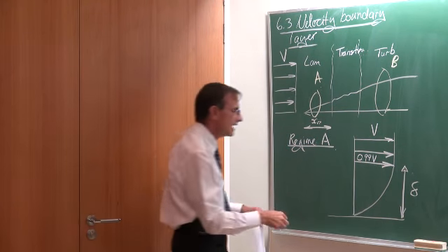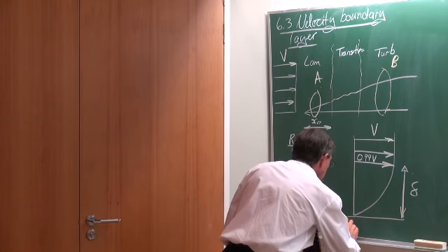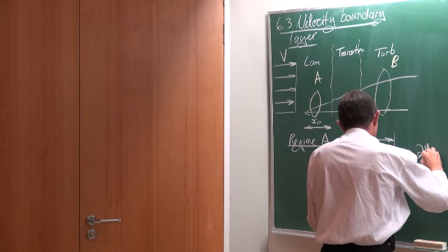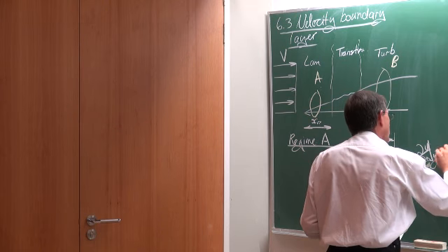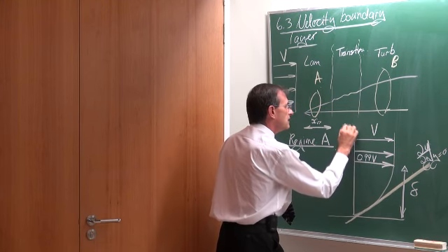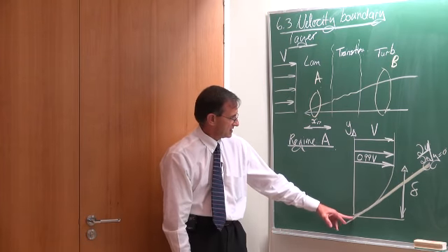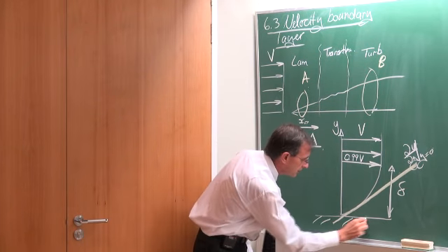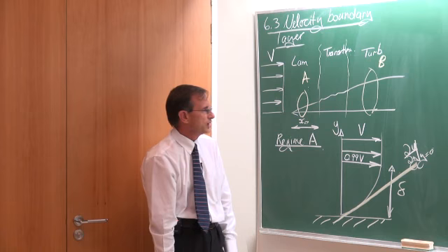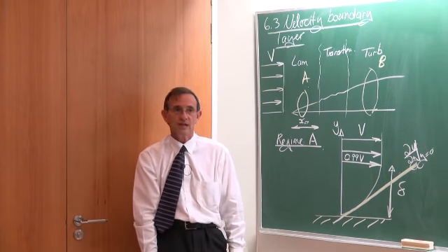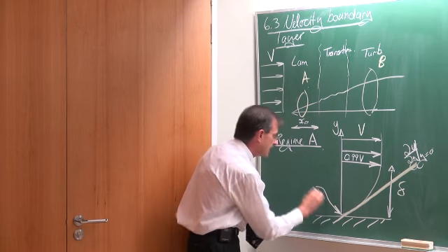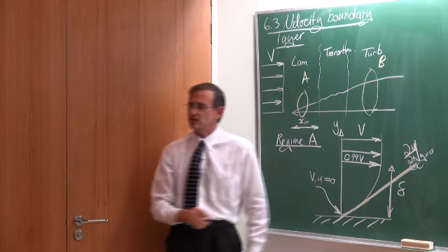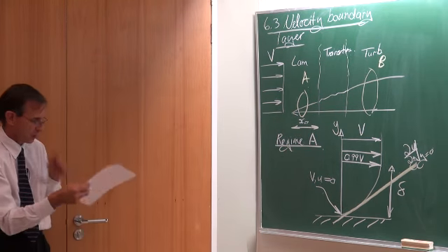Okay, and this gradient here is very, very important because it is equal to partial du/dy at y equal to 0, if we choose our x-y axes to start from the flat plate. It's the velocity gradient at that point, and we also know that at that point the velocity u or whatever you want to call it is equal to 0. There's a no-slip boundary condition on the wall.